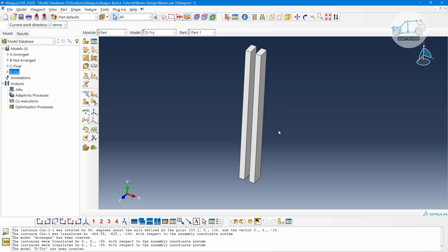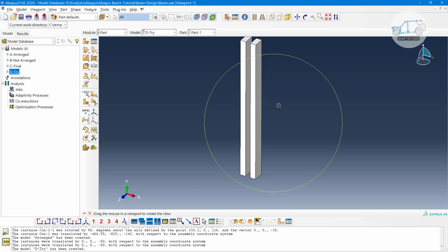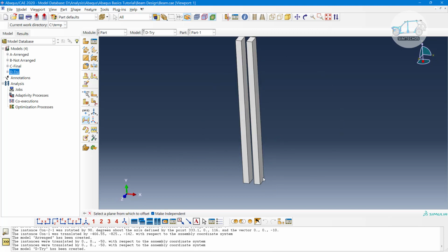So what I recommend is to always create a reference plane. So here we have the second option, reference plane. Of course, those are all options for the plane. The second option, and the most important point, make them independent. It means whatever geometrical modification you do will not affect the datum plane. So let's say I want to create a trapezoidal section here.